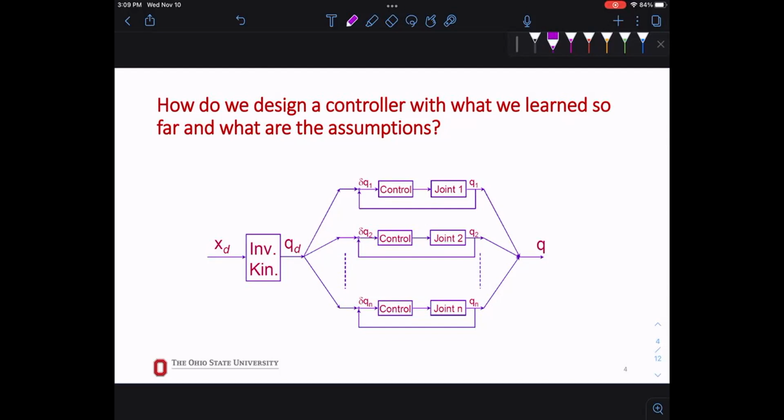There's a control inside to make sure it goes to this value. It gives us a vector that may or may not be the joint values we expected. Now we need to close the loop and check the error if there's any. What method can we use on the feedback loop to compare the joint values that we calculated with the desired position?